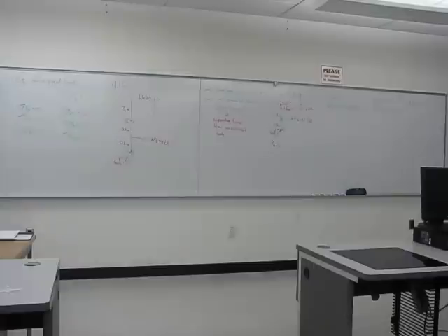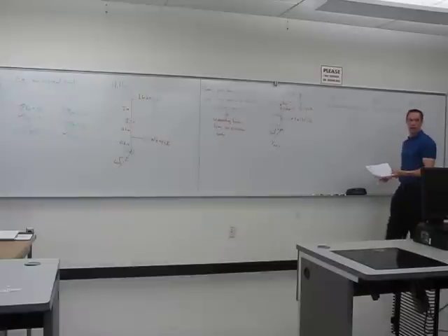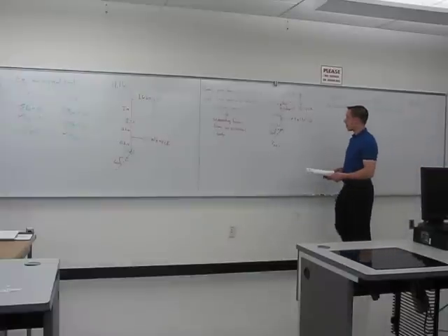So let's see if we can write this equation. Now, if we take the sum of the moments around C, because it's a 2-dimensional problem, all of these moments are in the z direction. So we're working with that third equation under the sum of the moments over there. The one that I checked off is the one that applies to 2-dimension problems. And in 2 dimensions, we can just use our F times D shortcut for all of these.